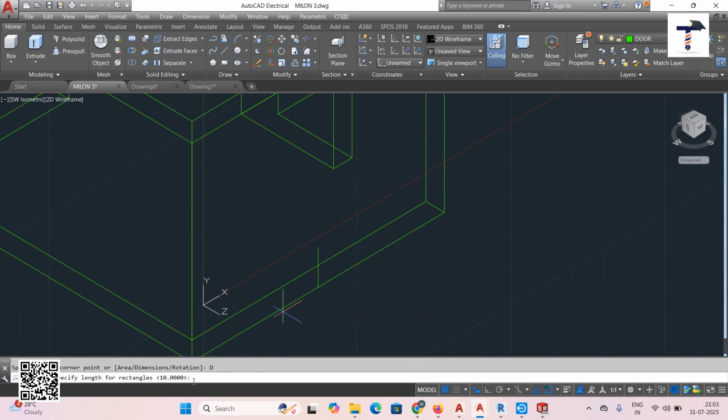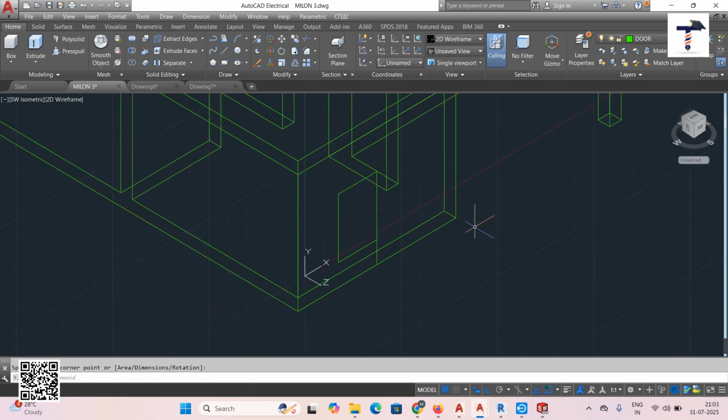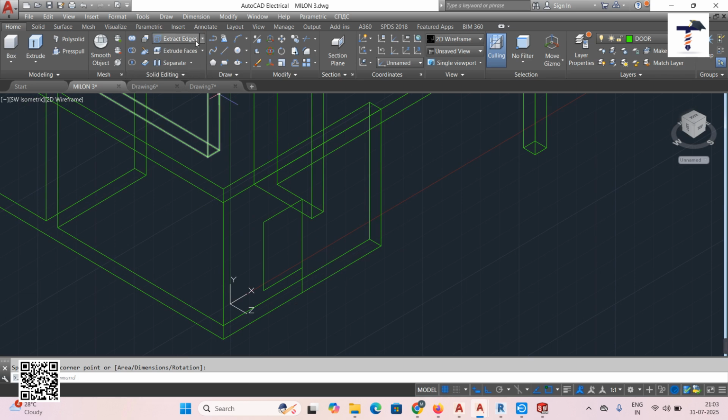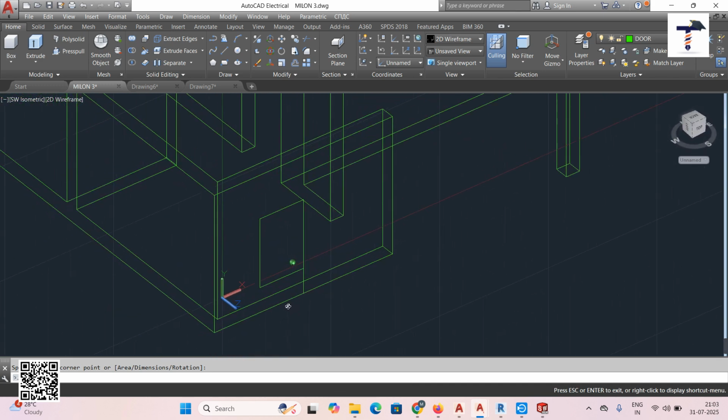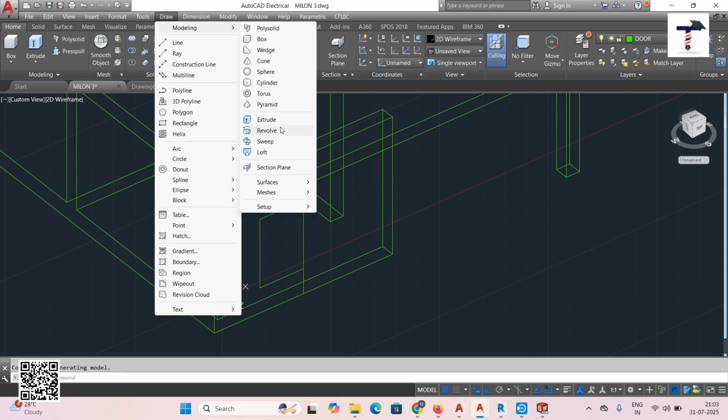Okay, you can put dimension from here, go to the dimension, suppose 20, enter, and suppose then 15, enter. Okay, so this one is too much. Suppose we create dimension here, suppose 1, enter, and then 1.5, enter. Okay, so now that is the 1 and 1.5. So that is one rectangle created here in meter. Then this rectangle is created on the outer surface, not on the inner face, the outer face.